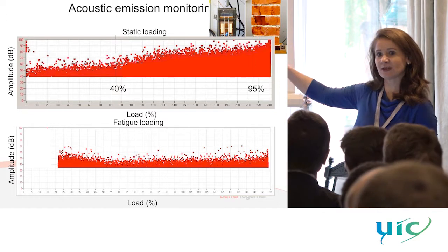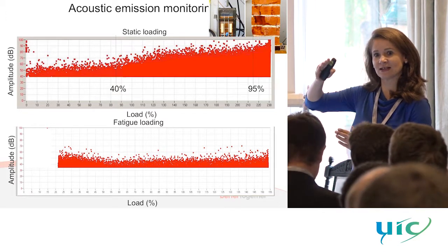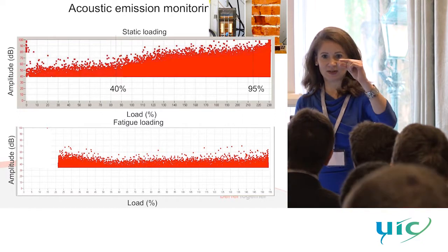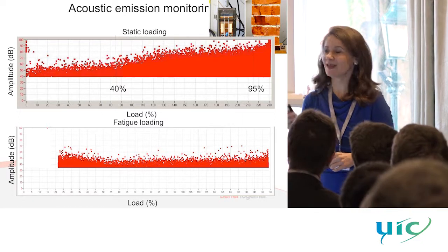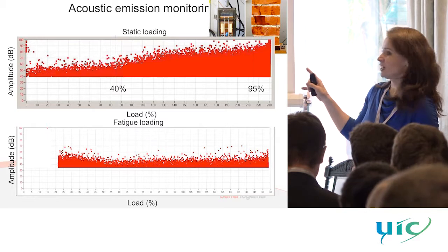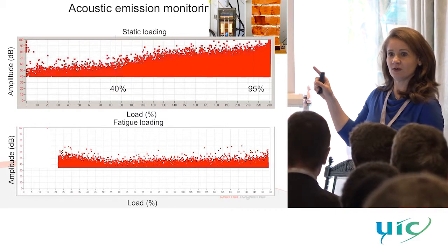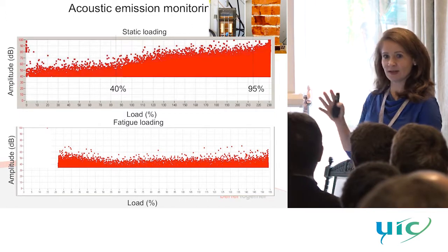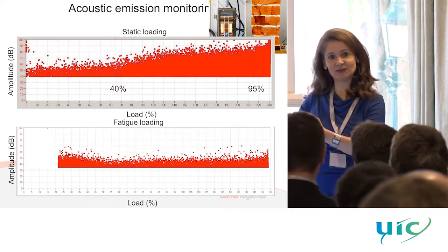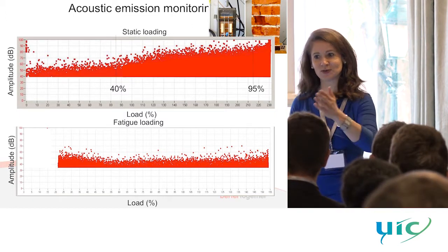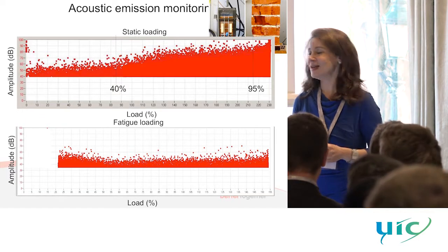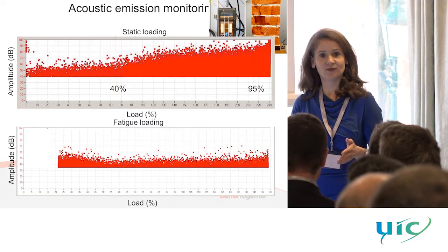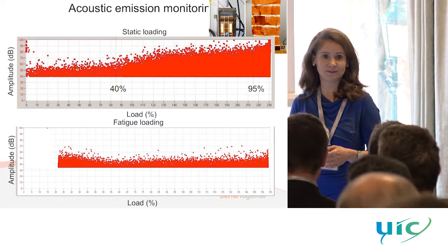Amplitude is on a log scale, so the vertical axis gets much more serious at every small step. So there is a change in behavior after 40% and after 90%. If you think about elastic and plastic regions in stress strain diagrams, which you're probably familiar with, up to 40% is about the elastic limit, and over 40% is the plastic region.